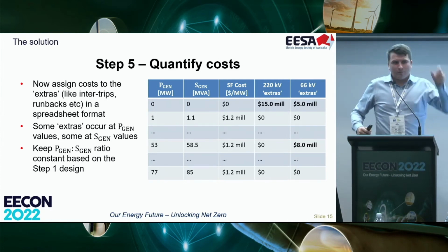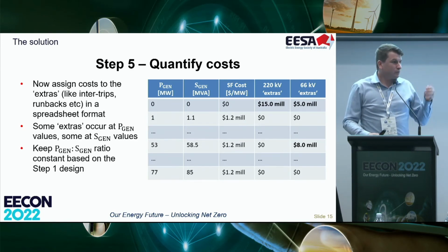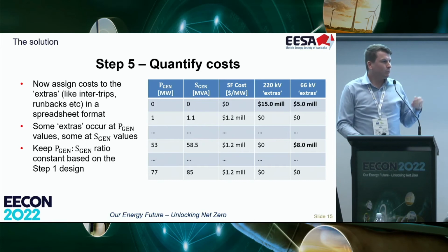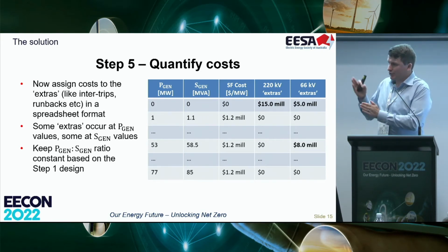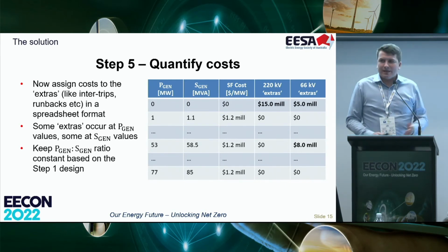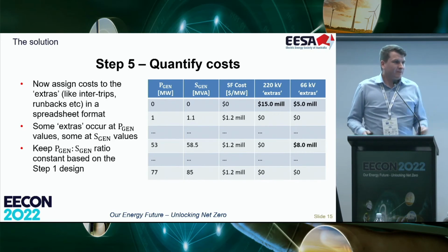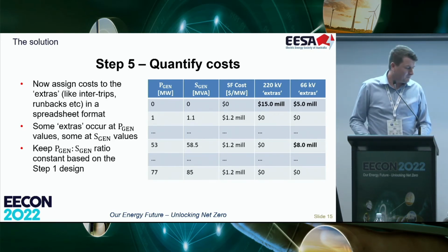We've got P and we've got S, and we step it up in 1 megawatts. If everyone's wondering why we're interested in 1 megawatts, it's because integer megawatts is the registered capacity limit. You'll need to have an integer number for AMO. You can't have an intermediate number. And you can calculate how much a solar farm costs. I don't know, let's call it 1.2 million. You can't hold me to it because I haven't told you what currency it's in.